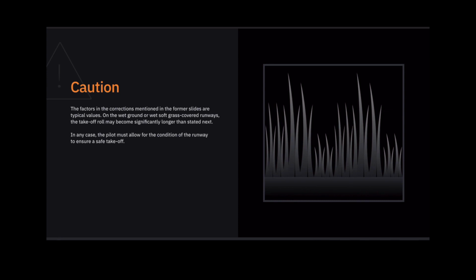Caution. The factors and the corrections mentioned in the former slides are typical values. On the wet ground, or wet soft grass-covered runways, the takeoff roll may become significantly longer than stated. In any case, the pilot must allow for the condition of the runway to ensure a safe takeoff.